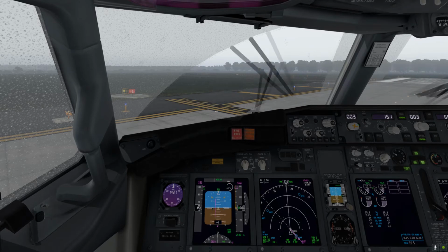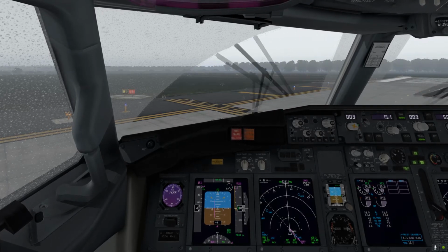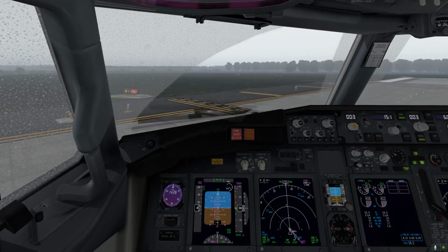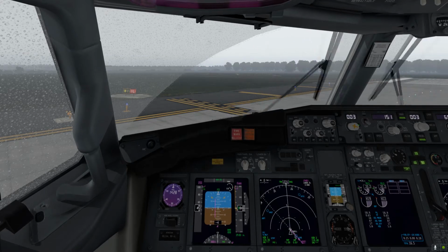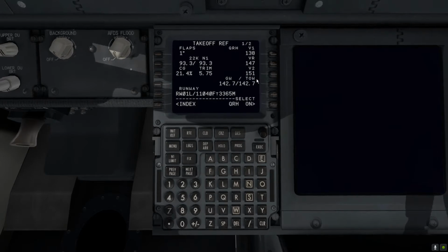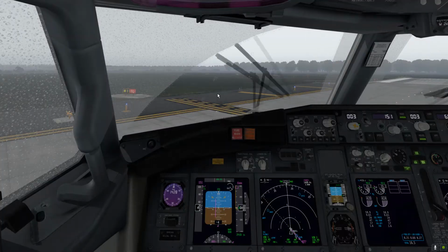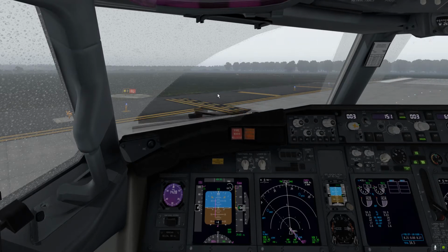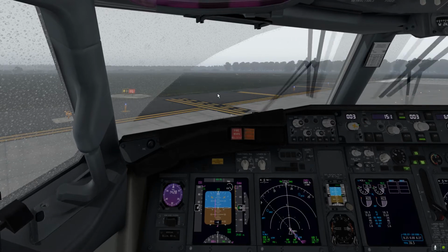SID runway or intersection change. So it says FMC, TODC, flap, derate and stab trim updated, and they have been updated. Radios and takeoff briefing is set and completed. Takeoff speeds, now we have 138, 147 and 151, and MCP says V2 151, heading 003 and altitude 6,000 feet. So the checklist has been completed, and we can now accept the departure.